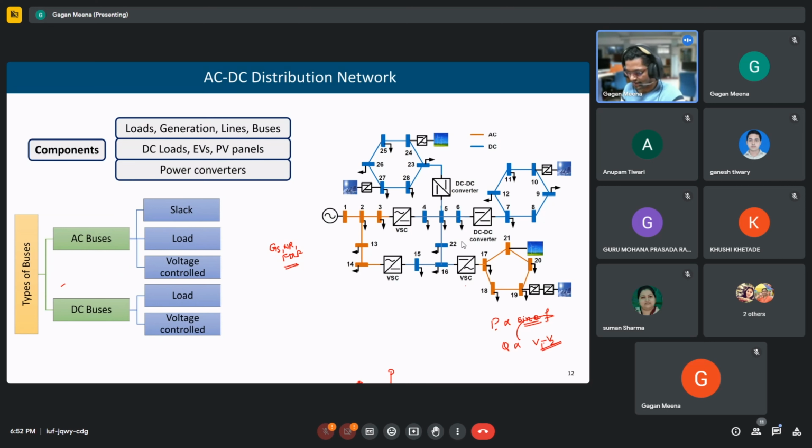So these are the different power flow algorithms that we are able to use for the transmission system, but we are not able to use them for the distribution system because of high R by X ratio. Also in the distribution system, earlier it was almost radial. Meshes are there in between to increase reliability, but those are used only when there is some problem, some contingency or fault. But usually the distribution system used to operate, or still operates, in radial fashion only.